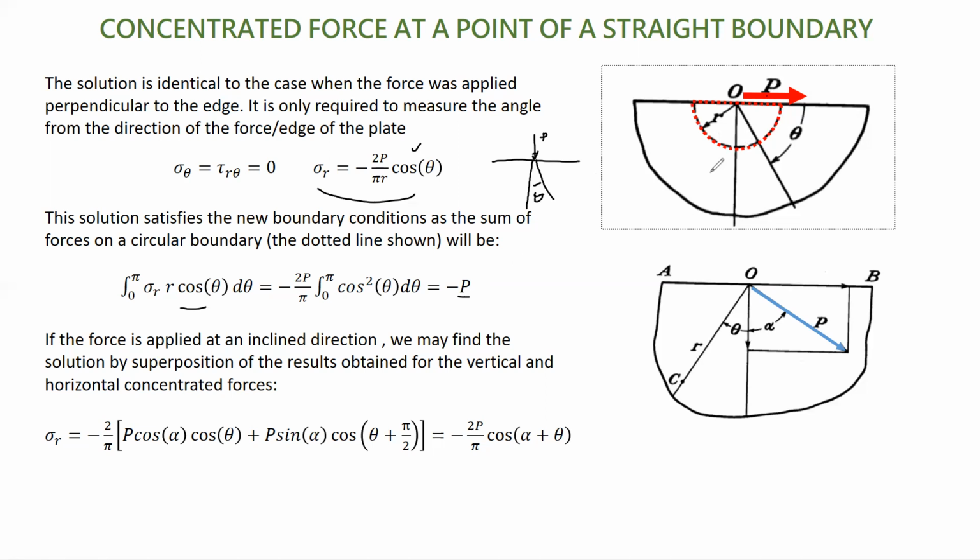Now, what about if a concentrated force is applied at point O at certain angle, not horizontal, not vertical? Obviously, I can add up those two solutions that we derived before. But remember, theta here in that solution and theta in the previous solution with the vertical line would not be the same.